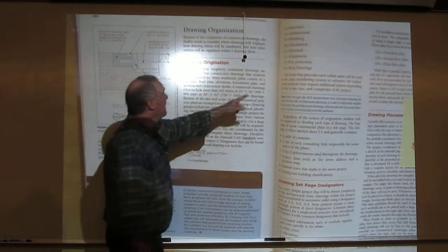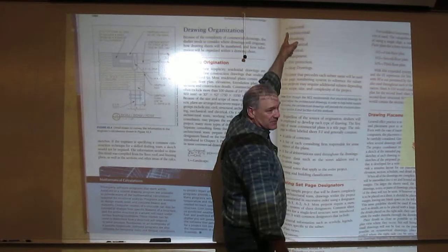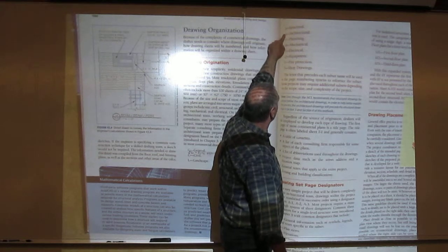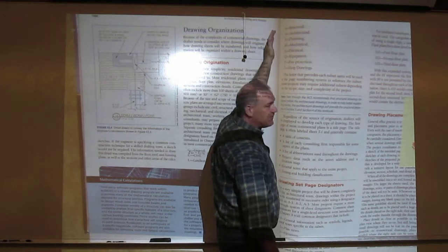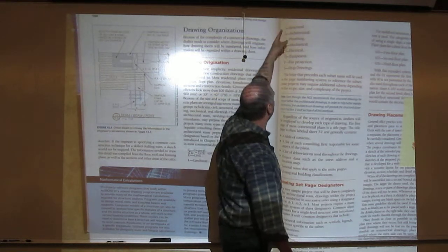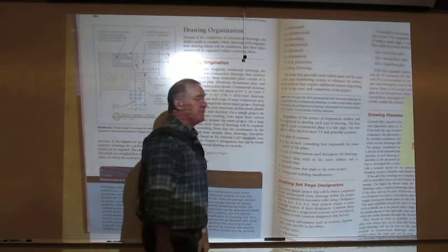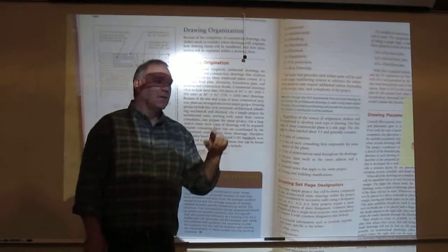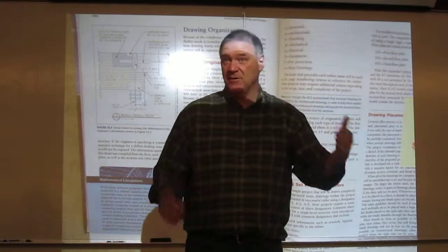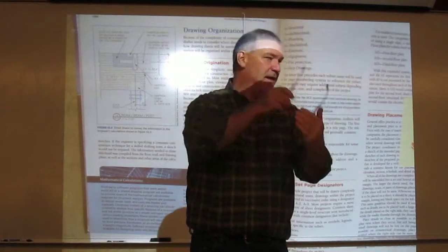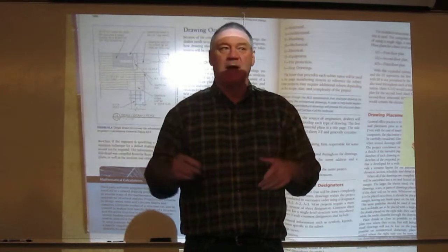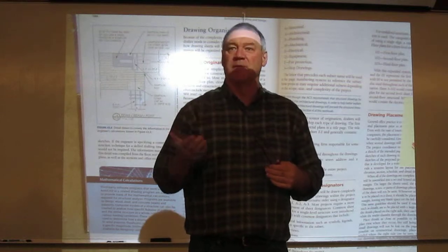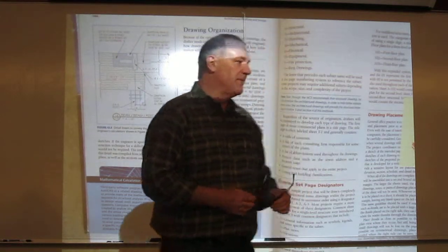Those are SDs. Then you go civil, they're the next people on here. Landscape follows that. Then generally the structural follows architectural for most people, but then you go architectural, and then all of your engineering type drawings come in, where you have S for structural, P for plumbing, M mechanical, E electrical. So on your drawing name, you'll always see that first. If I'm doing an architectural set, it would be A dash something. And we're just calling our sheet 1 of 8, 2 of 8, or whatever. This naming convention would be followed.